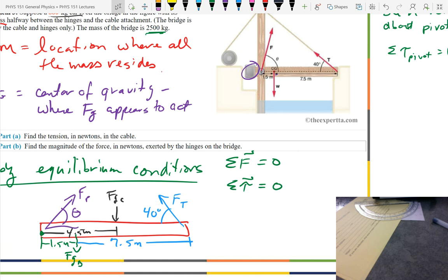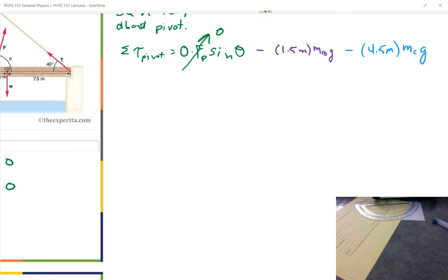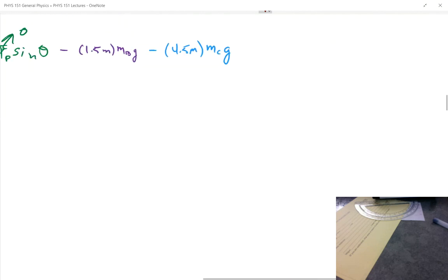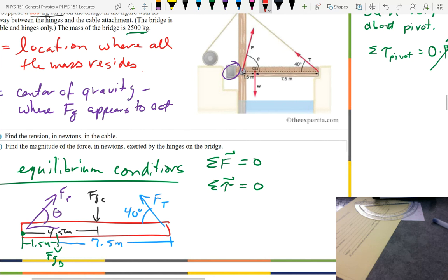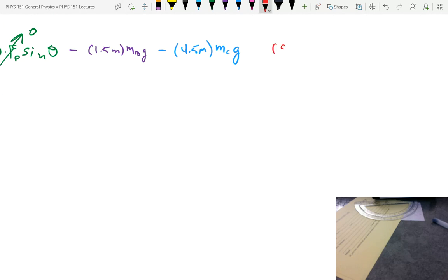It'd be a negative, for exactly the same reason that Edward gave us. It would make it rotate clockwise, or you can use the right-hand rule. So that's a negative. Now for the final one, Brandon, our final force is the tension. What's the radius for the tension? Okay, so we have 9 meters. I've got to at least put 2 sig figs here, 9.0 meters.